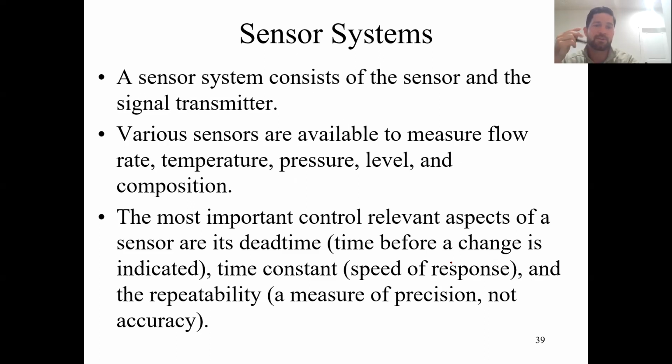Okay, so for sensor systems, I want to talk about some terminology first, and then we'll look at a flow sensor. For this class, you should be familiar with sensors that are used to measure flow rates. So we'll have sensors for flow rates. That'll typically be an orifice plate. We'll have sensors for temperature, and you've seen some of these before, like thermocouples, thermistors, thermometers, pressure, level, and composition. Many of these you might have seen before already in unit ops with hardware exercises.